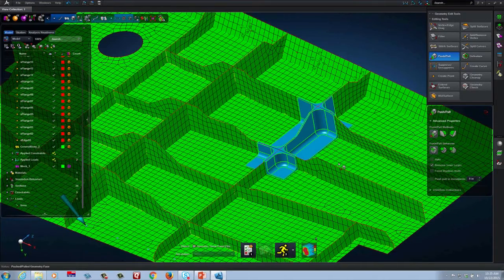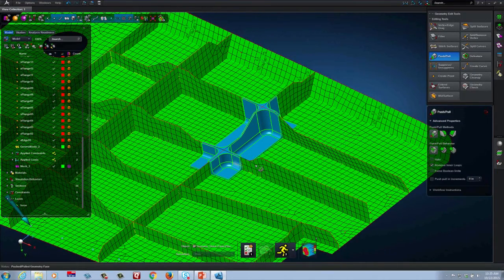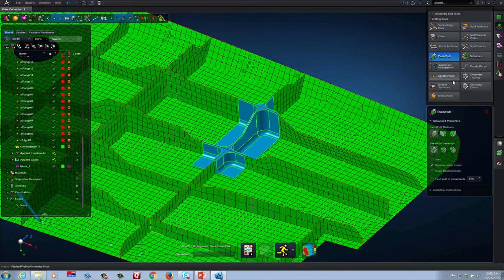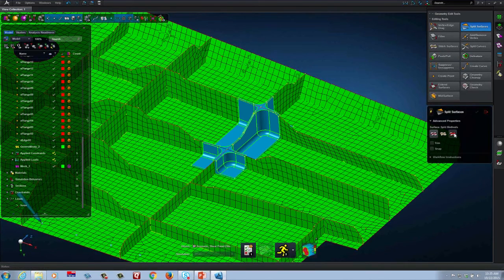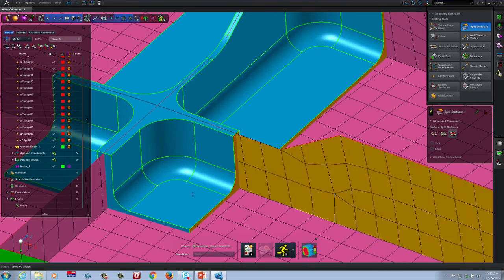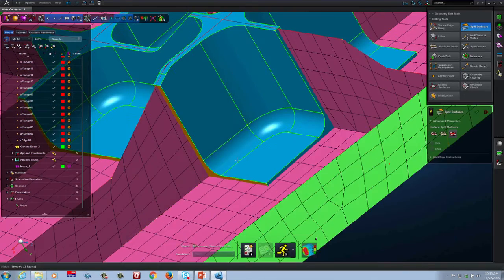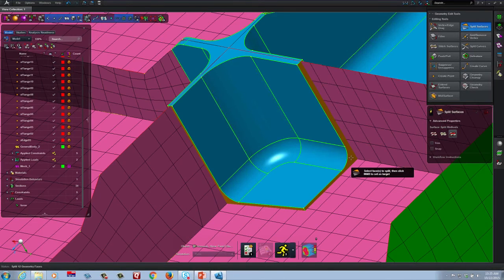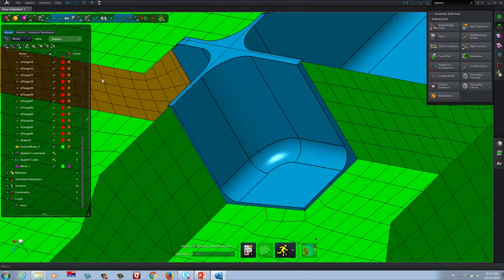Okay, I would like to replace, in my shell mesh, the shell mesh portion that represents where this solid is. That sounds like a tongue twister. So we'll come in now and split all of these surfaces on the shell mesh representation. I will select what I want to split, and I want to split at these faces of the solid. And we want to integrate this solid. We're going to mesh it, but we're going to integrate this into the existing coarser grid shell mesh.